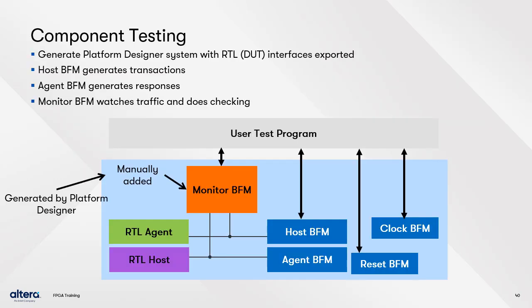To test an individual component, first create a Platform Designer system that has the component interfaces exported. Then when you generate a test bench system, clock, reset, agent, and host BFMs will be inserted automatically for you. If you're testing a host interface, an agent BFM will be inserted that allows your test program to issue commands. Monitor BFMs can be used to watch traffic and do coverage and protocol checking, but they will need to be manually inserted into a Platform Designer system.